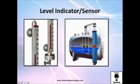So you may have this type. Actually, I used them before. You have it right here, and they move, and they make a pressure right here. So eventually you can go and read it right here, and you check out, and you see, oh, it's 60 centimeters. Normally, when you measure level, you measure it in centimeters or meters. You don't measure cubic meters or so. The level is normally measured in length units.